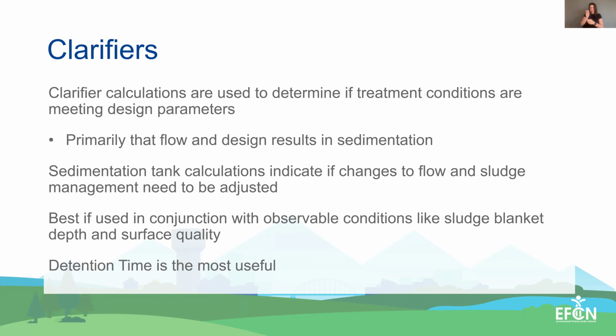We're not going to talk about detention time today because we did that in our last webinar. But for example, if we know what our design detention time is for our clarifier, and we notice that sludge is starting to become septic and float to the top, we can go to the drawing board and ask, okay, what are our dimensions? What's our flow? Or do we have the correct detention time, or is that what's resulting in this condition? So while these calculations help us, a lot of the time they're more like concrete proof to ask, what is the issue here, and how do we adjust it based on these conditions? That's why, a lot of times for our clarifiers, detention time is so useful.